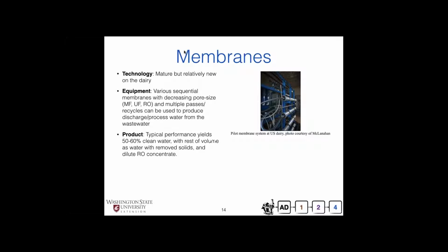And it's made to produce water that's ready for some other use. And we can look at this in more detail offline, but we really want to set the target is what we would look for. So typical performance, 50 to 60% clean water, and then the remainder of that would still be considered for other water uses. Biggest challenges here again is it's highly dependent on the upstream processes, and so solids control, and then really setting the system to our particular application.